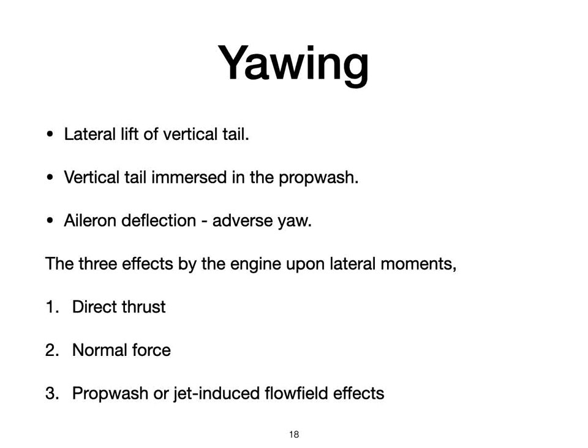The three effects by the engine upon lateral moments, which are the same as for longitudinal moments, are direct thrust, which is in yaw, the thrust is balanced unless an engine fails. Second one, normal force. The inlet front face or propeller disc has the same normal force term discussed for longitudinal stability. That is, the normal force due to the turning of the air at an inlet front face, FP, can be calculated from momentum considerations.